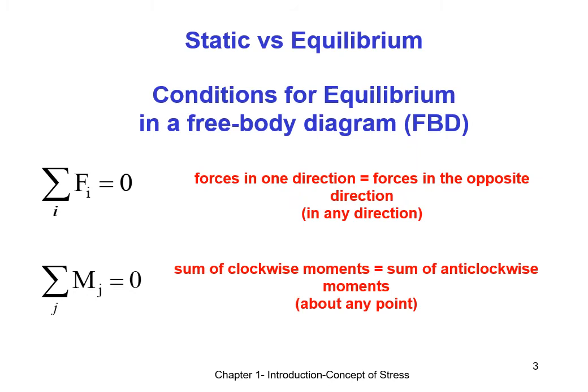In tutorial 1, we'll cover the concept of stresses. In this course, we are only considering static equilibrium. Static refers to zero velocity, meaning stationary. Equilibrium refers to a case where all the forces and moments are balanced in all directions and axes of rotation. Mathematically, we write this as the summation of forces in any direction to be 0 and the summation of moments about any point to be 0.